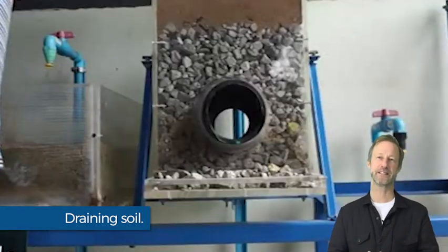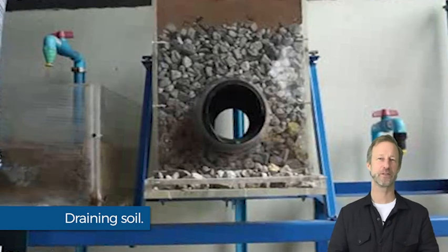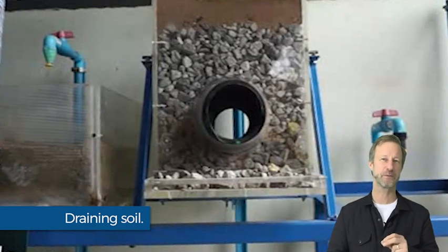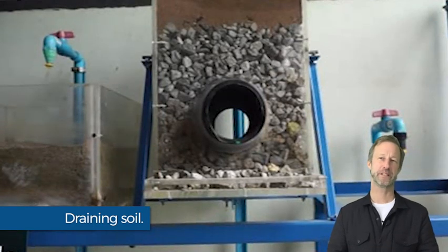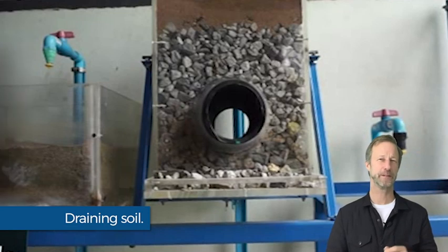We constructed this assembly housed inside an acrylic box so that we could test and visually see its performance. We used sand for the backfill material, and since the spaces between the drain rock aggregate are large, a good deal of that sand migrated to the spaces before we could even start the test. The bottom of the container has holes drilled so water can exit the system and is visible when it's through the assembly.